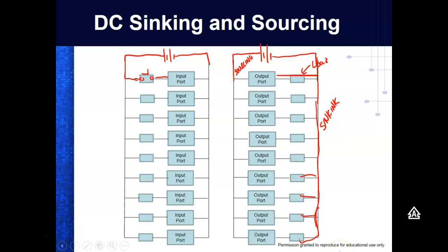Now down here, since this is a relay output, let's look at the commons on here. Y'all look real close. It should have AC/DC, AC/DC, AC/DC, AC/DC. Y'all see that? Okay. So what that means is if I wanted to use these relays to output AC, then I could jump the L2 over, right? Understand? But what we have is the plus jumped over, and every one of the commons are jumped together.